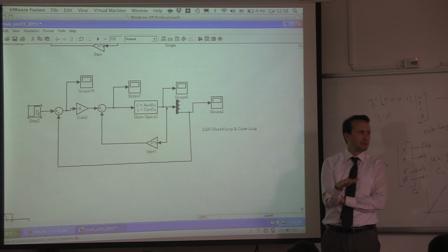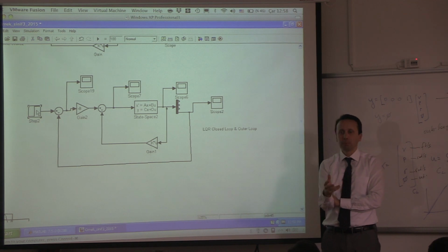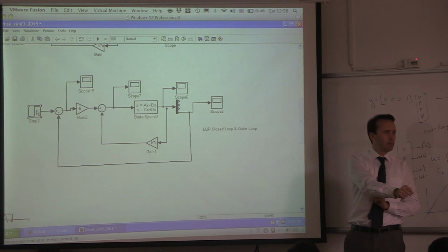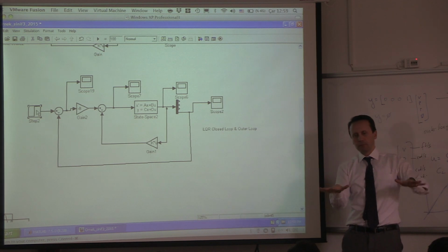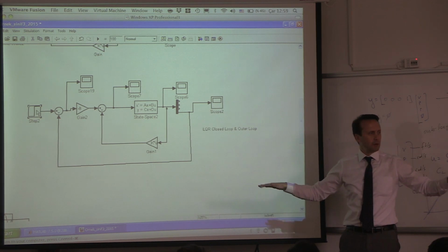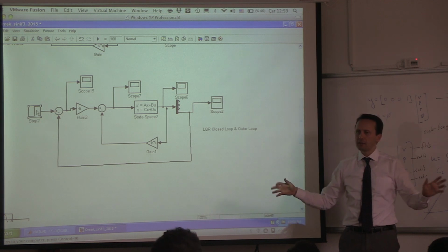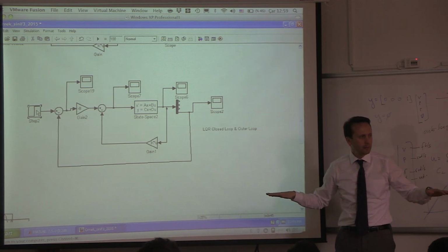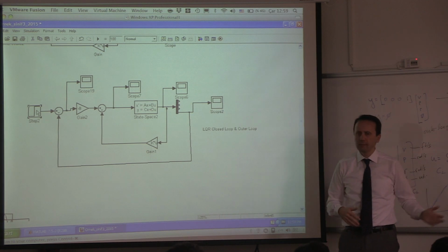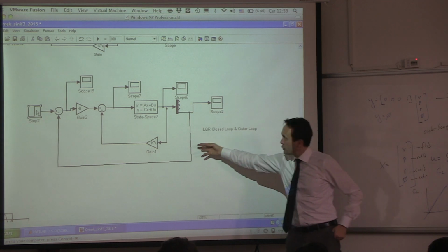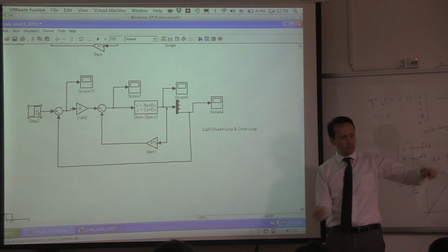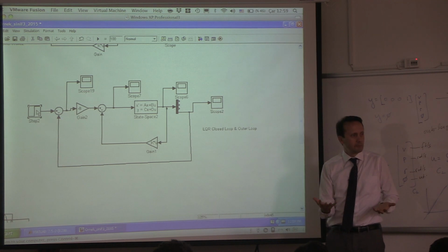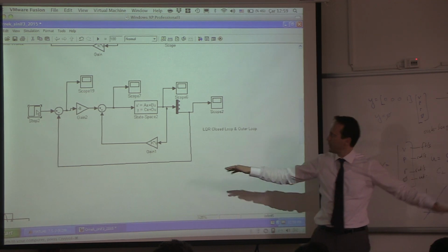And this is very typical in a lot of airplanes, including fighter airplanes. The pilot will know if you go to maximum, you will do this. If you do this, you will go to that. So you don't mess with the ailerons. You know your command is phi. Is there a disturbance? If there's a disturbance, turbulence, wind, I don't care. This controller will always try to make sure that the aircraft goes to the control input that I give. The ailerons will start doing this. They might be moving a lot.